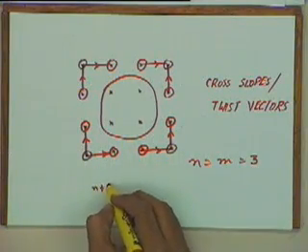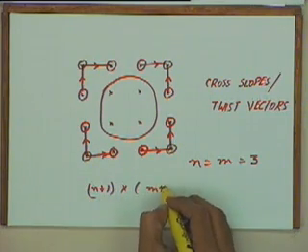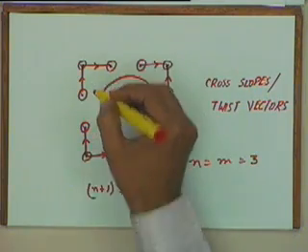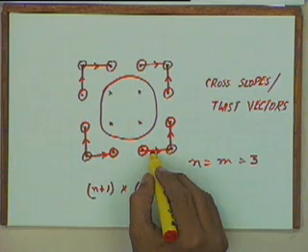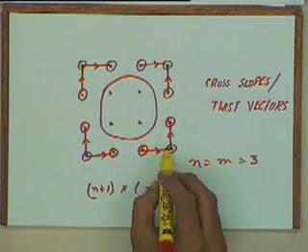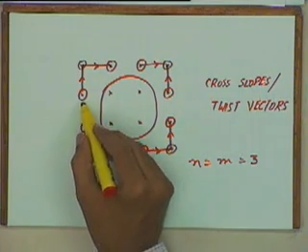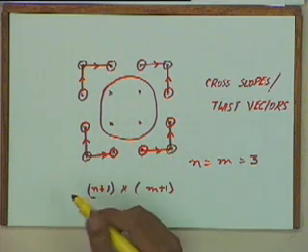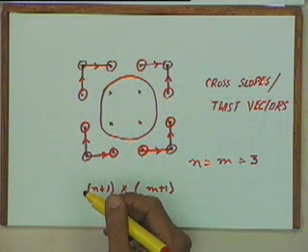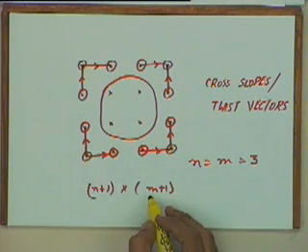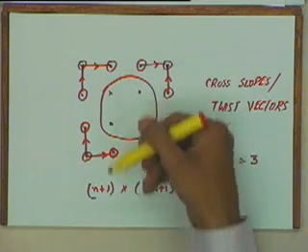Okay, similarly, if I have a higher degree Bezier surface, that means I have n plus 1 cross n plus 1 points. If I change any of these intermediate points, the continuity of the corners will never get affected. Continuity will be affected only by k points in this direction, k points in this direction. So if I want C1 continuity, only 1 point here and 1 point here will affect my continuity. So if n and m are large, that can be important in controlling the continuity in the case of composite surfaces.